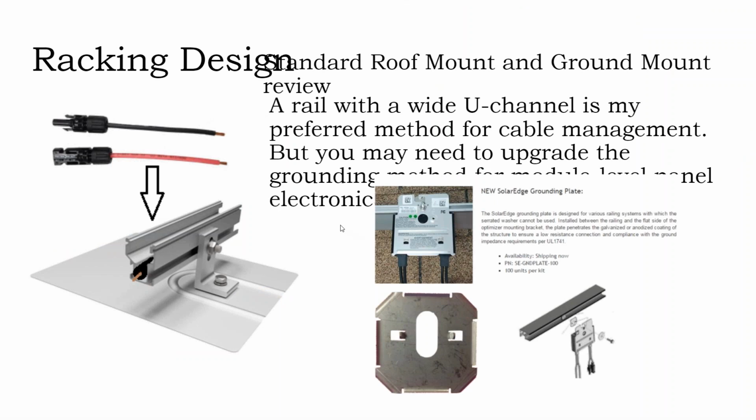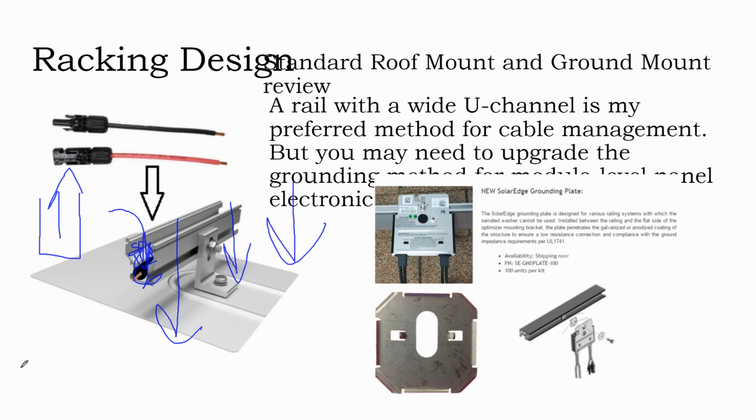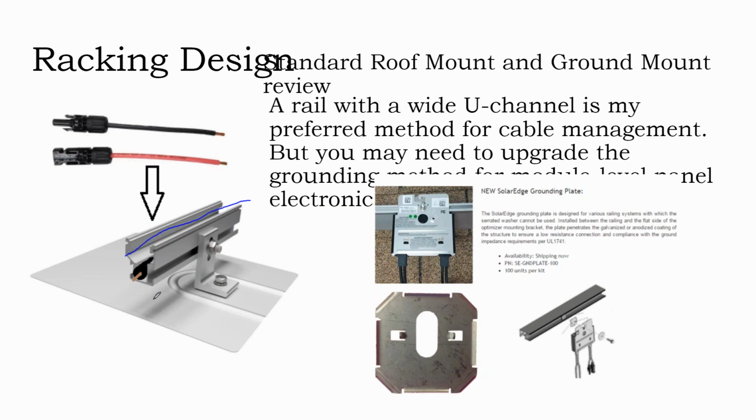And there are some fine elements of racking design. I prefer racking systems that have a wide U channel facing the top, because I like to take my cables and lay them into the rail. Other installers don't like that because they're concerned about water filling up in this U channel. But I drill holes into my rail to have any water drain out of it. I like this because of the physical protection from squirrels and critters and debris. I feel it's a safer design.